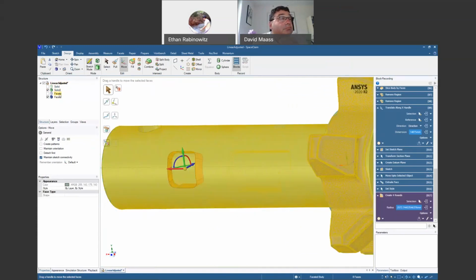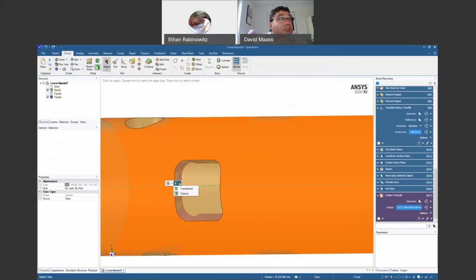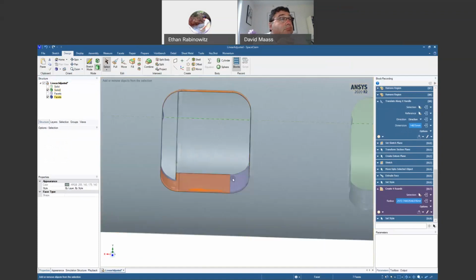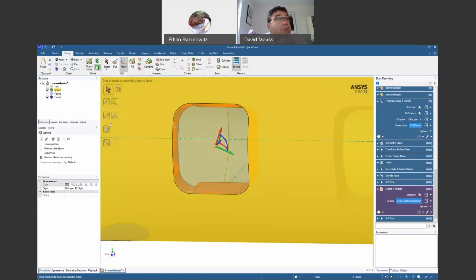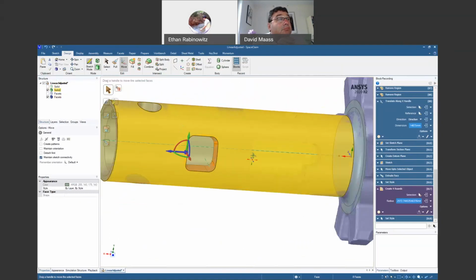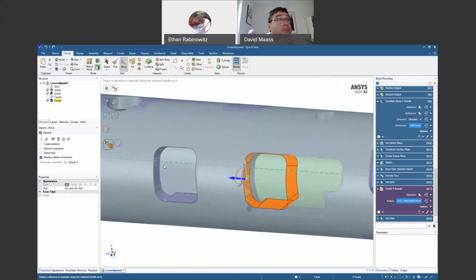And let me first make this body transparent. So what I would like to do is grab this hole with the move tool, and I'm going to put the move tool on its left face. And what you're able to do with this copy function is add up to it. So if you simply hold control while you do an up to and you pick a facet, it copies it up to that all in one shot.